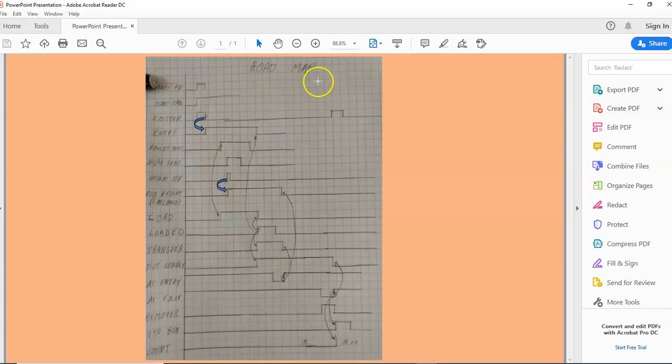And so you can create this roadmap, is what we like to call it. While this might not be totally accurate, it tells you, okay, when this pallet goes high, then you turn on this load signal. When this loaded signal goes high, then you turn off this conveyor and this conveyor. That's pretty much where we ended up in the first introductory view.